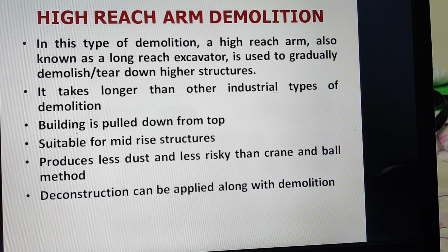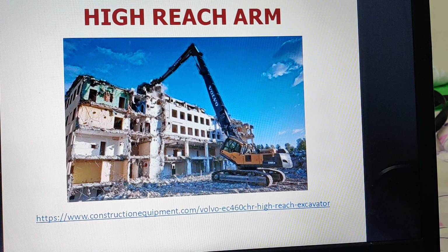Deconstruction techniques can be applied along with the demolition. See this example, a photo of which has been taken from the site given here. This long arm is there, and then one operator can do the demolition work, and he is quite safe as he is quite away from the building which is being demolished and the debris.